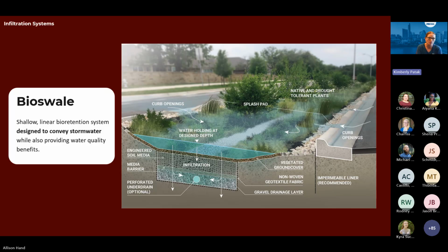It also serves as a great way of reducing the irrigation needs of an area. Say you want to do some great landscaping, but then you'd need to put in an irrigation system to keep that vegetation established. In this way, we combine multiple benefits: we have our vegetated area, but we also have natural water runoff coming in through each storm event to provide hydration to the plantings.